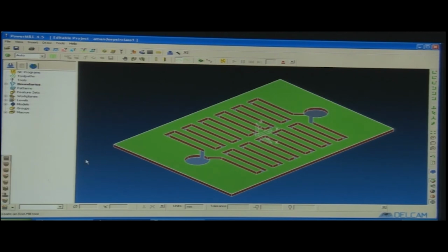Now, what are the tools here? The 3 points that I mentioned before: the machine tool, the cutting tool and the job. So, let us talk about the cutting tool here. What are the options? We have an end mill tool. What is the purpose of the end mill tool? It does the roughing; the major part of the material is removed using the end mill. Then the ball mill is generally used for finishing, then the tip radius tool, which is also called bull nose, then the tapered spherical tool, then tapered tip tools, and then a drill tool, with which normal drilling is possible.